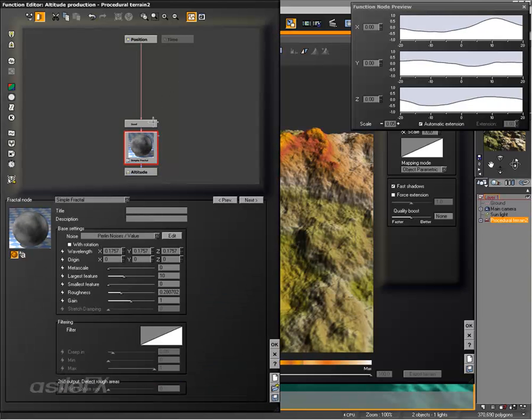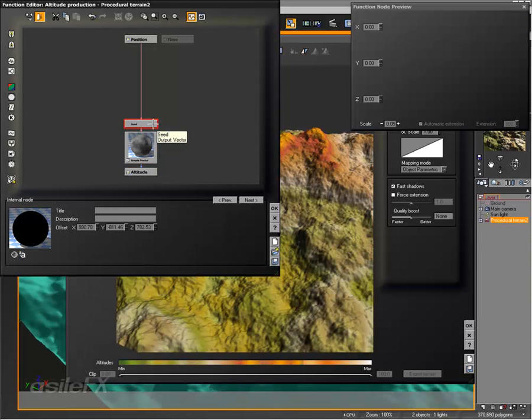Now there's another thing, and that has to do with the seed. This isn't always going to be an issue, but I have found sometimes you will run into problems using the seed node with ridiculous calculation times and lots of memory usage for simple displacements. The seed is an offset, but it works a little different from just an offset.